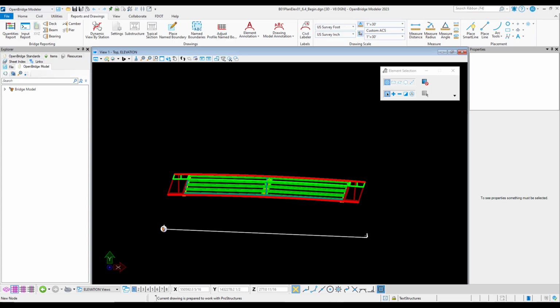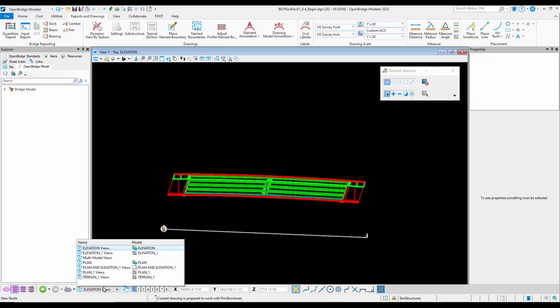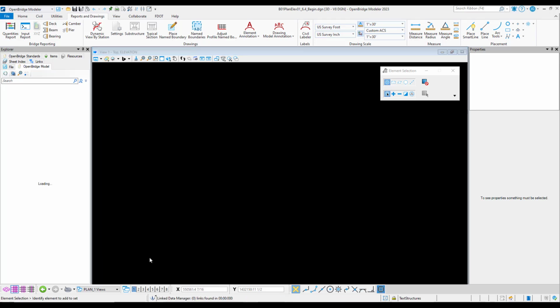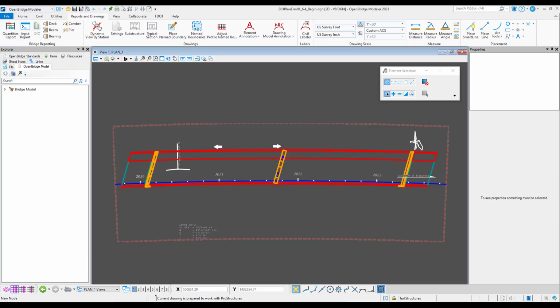Once you open that up, we're going to open our plan_1 drawing model. Go down to the view group drop down list and select that drawing model, plan_1. Next, we're just going to turn off the levels for any of our 3D line work. We don't want any of our callouts to be wrongly associated with a 3D component. We want to place it only on a support line.